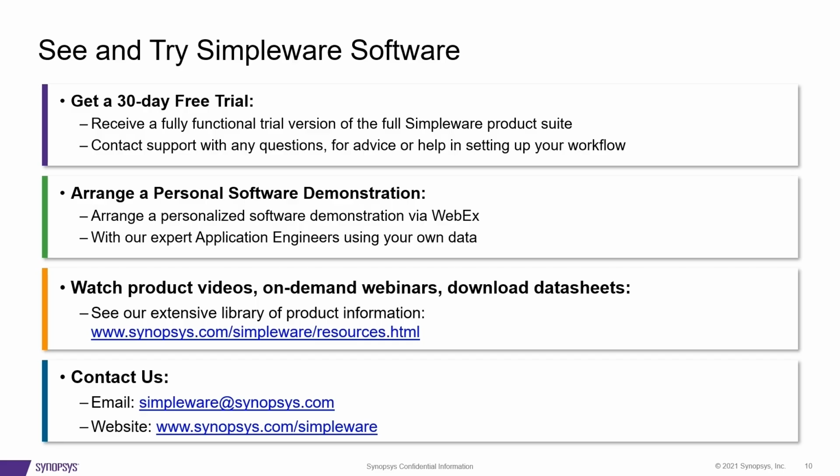Maybe Chris, you want to comment on the interactions between Simpleware and Abaqus? Sure. So in Simpleware, our model configuration has a dedicated export for Abaqus, the INP file. Here you can set up the materials, contacts, node sets, shells as required. So those are the workflow steps that would typically be used for going from Simpleware into Abaqus.